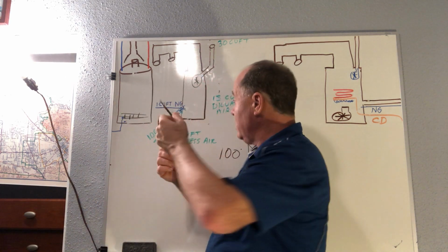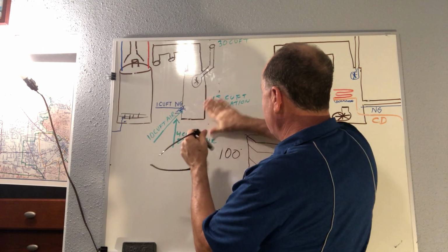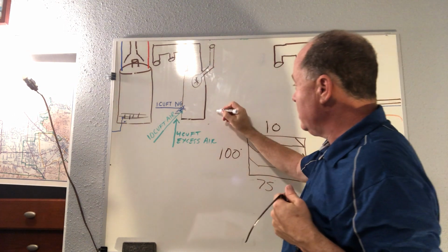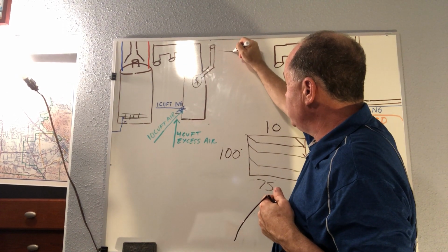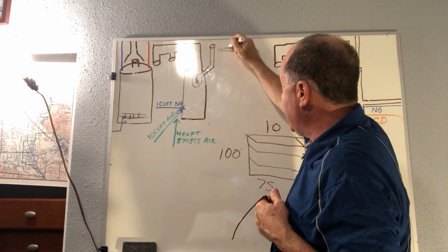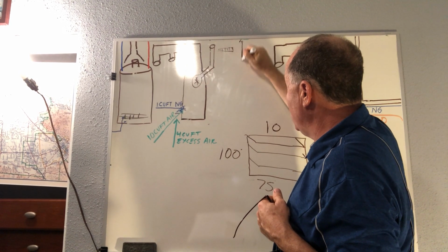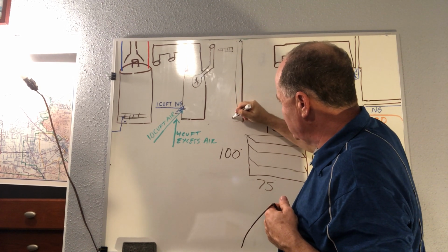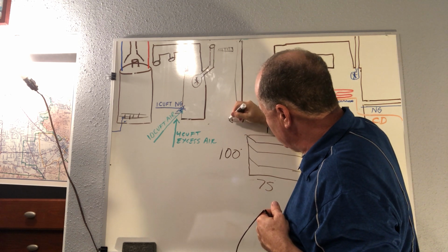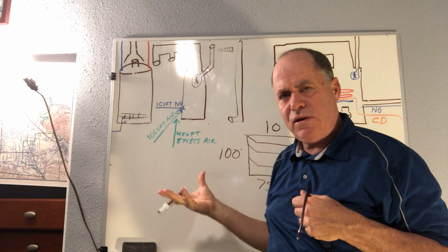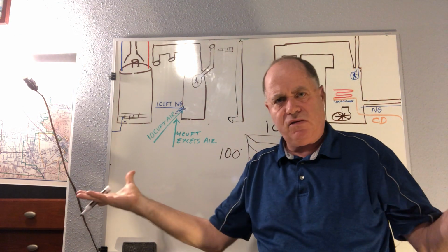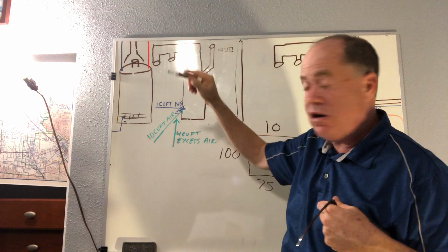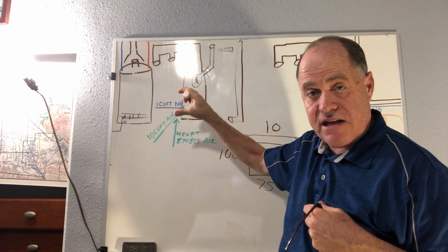Okay, so what we're talking about is that a lot of times for furnaces like this, in the closet, you're going to have probably a screen vent up here going from the attic that can bring air into your closet. But then you also have a duct that you'll see like this that comes down, and it just sticks out like that. And it always looks weird. You're like, there's this duct that goes nowhere. It's just open. What is this? Again, that's so that the cool air can come and flow through, and that you have a nice flow of air in your closet or in your enclosed space, right?